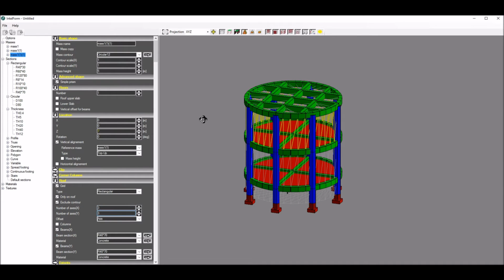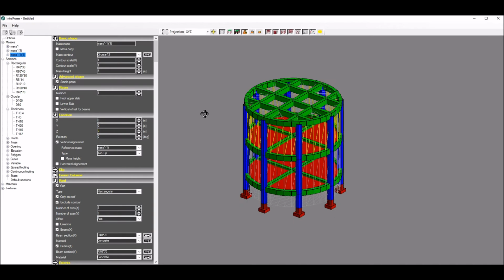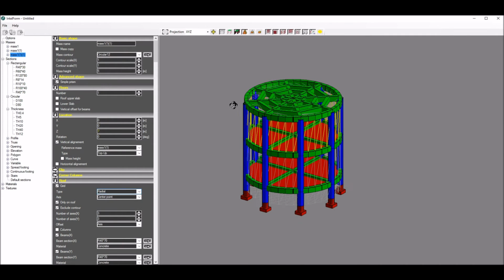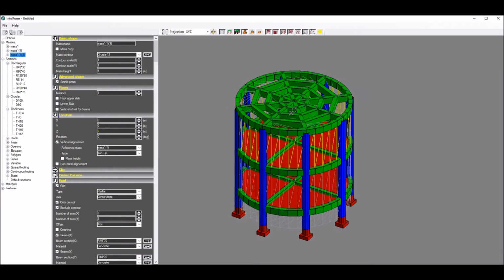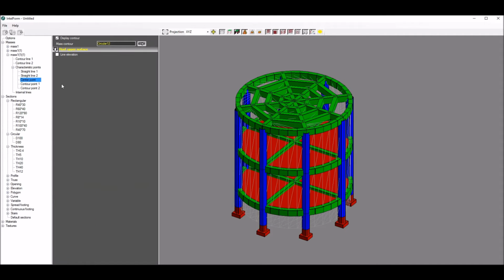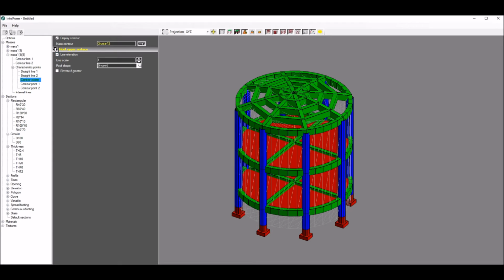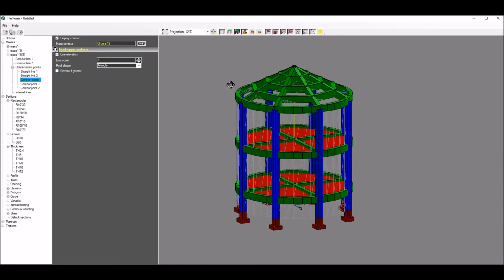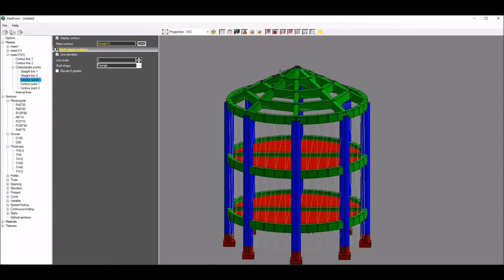Let's define our roof in the form of cone. First, I define some parameters for grid, number of axes and grid type. In this case, I choose radial grid. Now I choose one of predefined points, namely contour center point, and I elevate it to required height. We can form our roof by choosing predefined or user-defined curve as a roof shape parameter. For cone, I set a triangle.